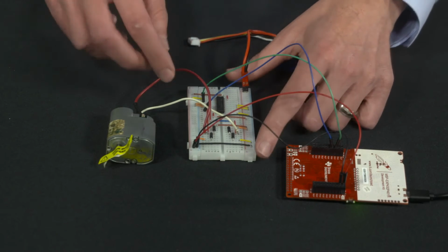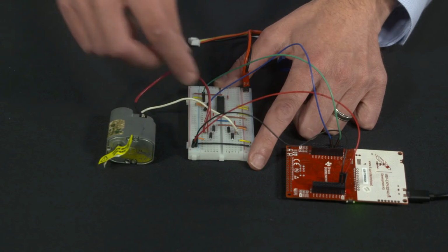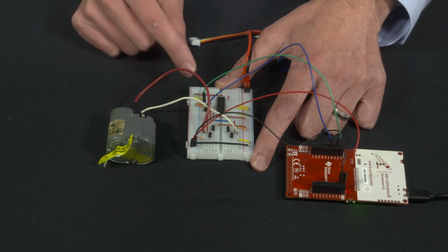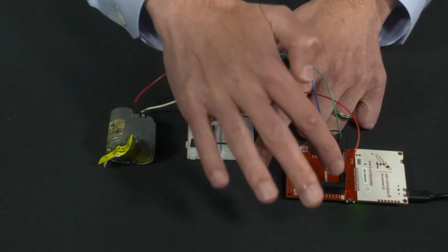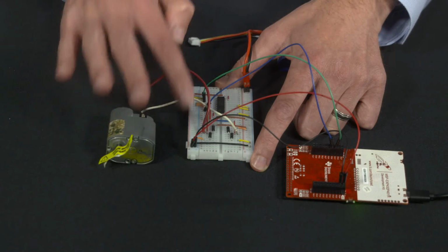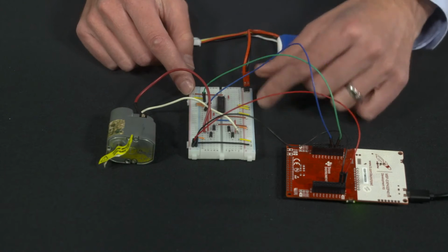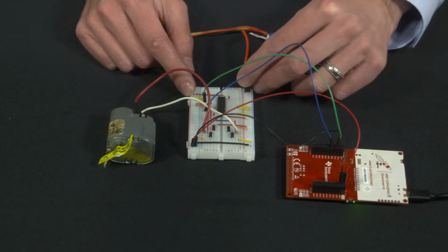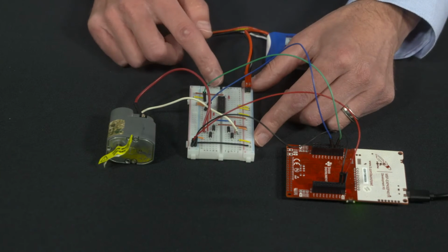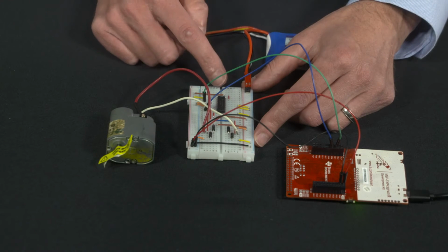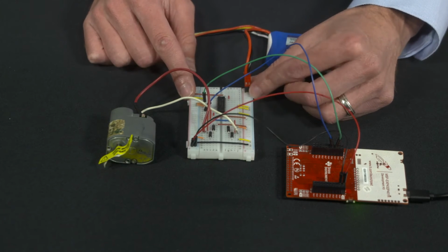A couple other things to note. First, we've connected a common ground between our microcontroller, this black wire, and our breadboard. So that black wire is our common ground hooking in right here. We also provide power to the H-bridge via this 5-volt output on our launchpad board. Finally, this battery plugs in on this side of the breadboard, and that battery is going to be used to drive the motor. And so essentially this H-bridge kind of spans the gap between the low power side of our circuit and the high power side.